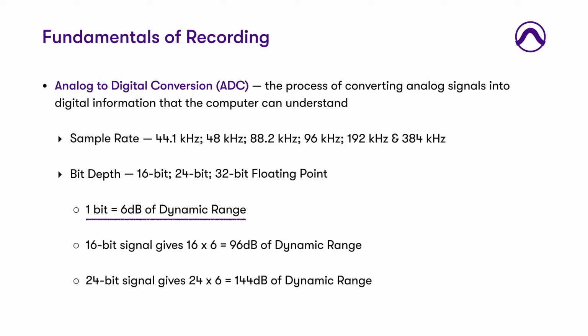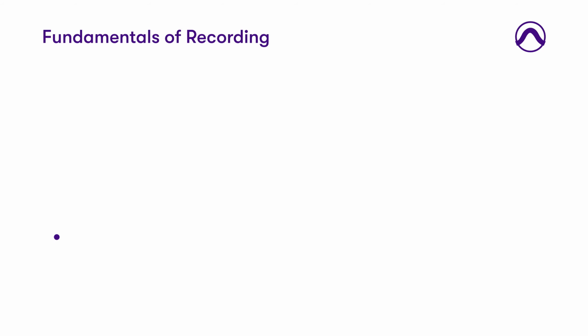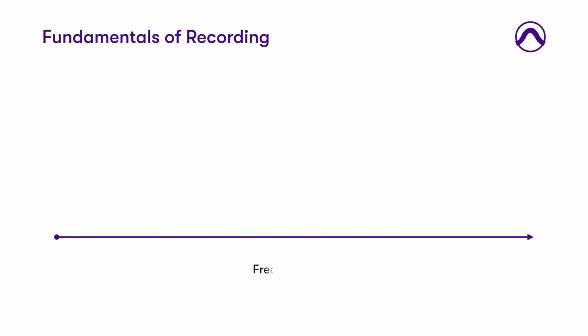Many of you may be wondering why the sample rates that we use in recordings are such an odd number, like 44,100 samples per second or 88,200 samples per second. What is the rationale behind using such a number? Why not just use a nice rounded 50,000 or 100,000 samples per second instead? These numbers may seem random, but they actually have to do with our, that is, the human, hearing range.